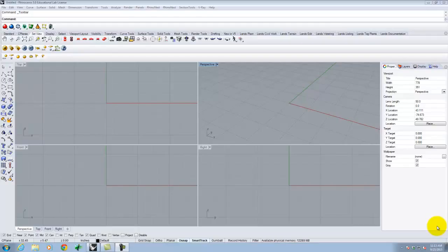So I use it, and we spend a lot of time on topography, but it's not limited to topography. It's really showing you a variety of ways of working and manipulating these materials. So today we're actually going to get our topography information from SketchUp. I used to do an exercise where I gave everybody a flat set of topo curves, and then we moved them up in space and we created the surface out of those curves, which is certainly one way of doing it. Generally, for the approximations that we're doing, working with a SketchUp file is a pretty easy, free way of getting terrain information. It's not perfectly accurate, but it's reasonable.